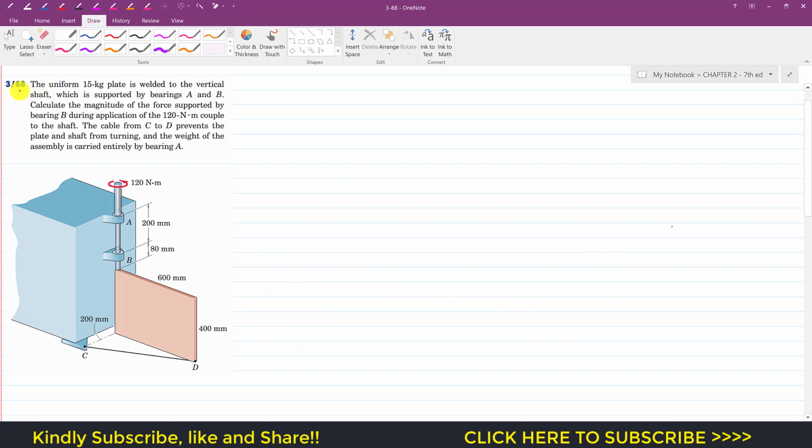This is chapter 3, problem 88. The problem says that the uniform 15 kg plate is welded to the vertical shaft, which is supported by bearings A and B. Calculate the magnitude of the force supported by bearing B during the application of the 120 Newton meter couple to the shaft. The cable from C to D prevents the plate and shaft from turning, and the weight of the assembly is carried entirely by bearing A.